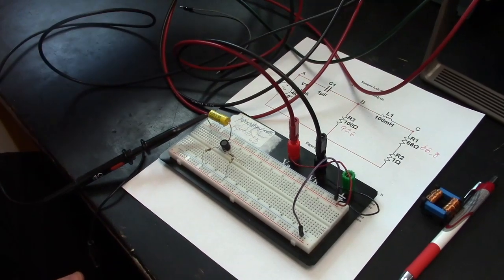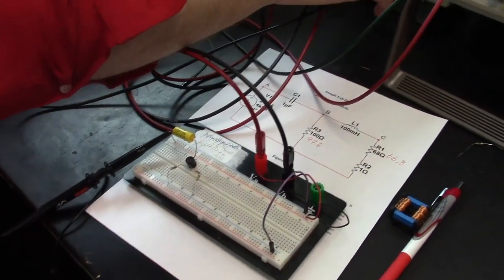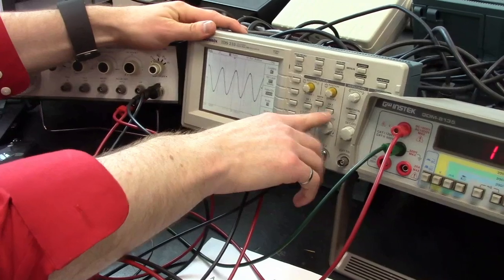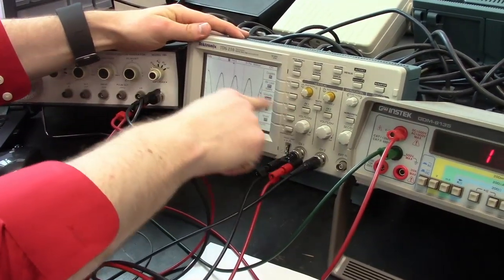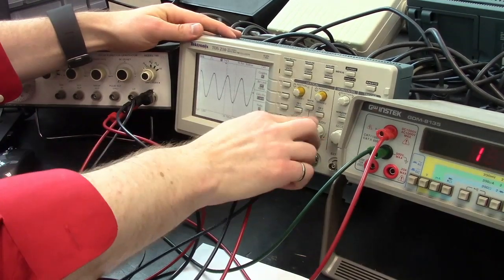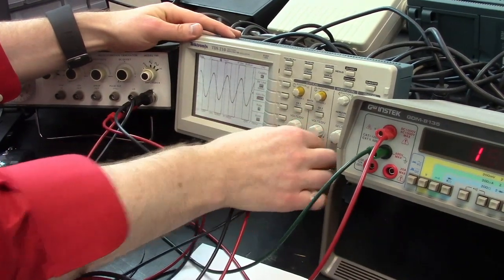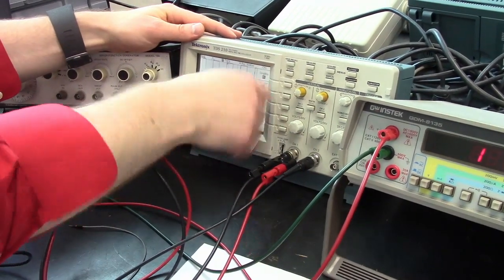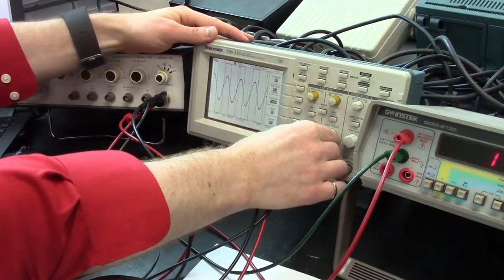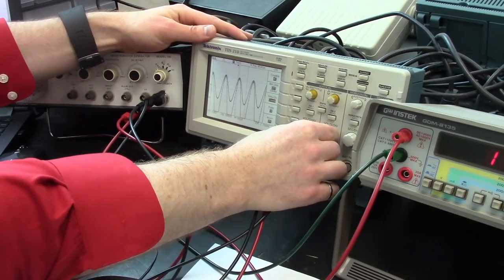So we see that we've got channel 2 turned on. If channel 2 has disappeared, then you can hit the menu button twice and that'll toggle the display of that. You could also turn channel 1 off, now you don't see anything. Channel 1 now displayed again. Turning on channel 2, then we'll turn up the volts per division, so turning down the size of the signal by rotating this to the left.